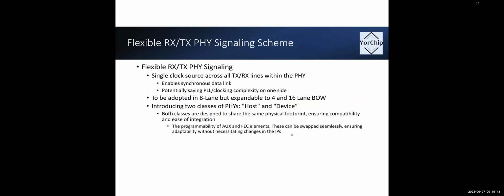Yeah. So latency matters, but a lot of times the device that's sitting on the other side is, say, an ADC, right? So it does benefit from being able to pump synchronous data to the other side without any interrupt. So there are a lot of intricacies where having a synchronous link would help. One of them is latency, but also things like time stamping.